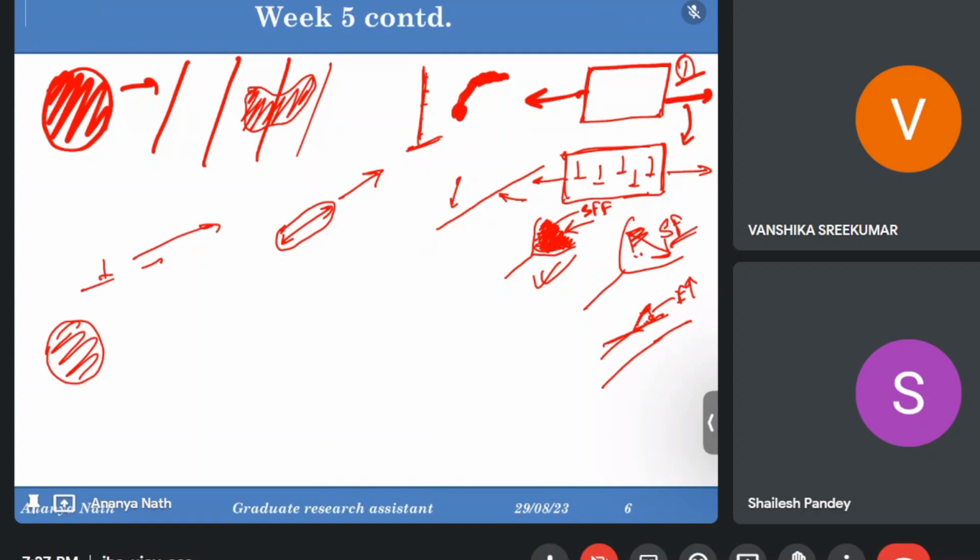But yeah. So from lecture 4, the new topic was started, that is recovery and recrystallization. For overaging, we have seen that for heat treatable alloys, we did the strain hardening by aging, by natural aging and artificial aging. And after that, if we keep the material for a longer time or at a higher temperature, the overaging happens.